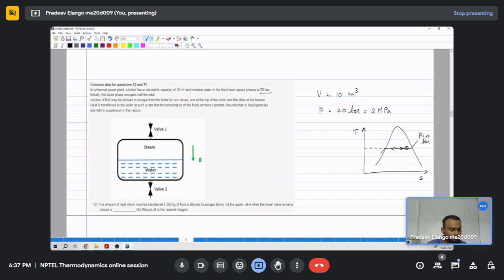In the solution they have given the dryness fraction. So when 300 kg of the steam is taken out and that enthalpy has to be calculated, it should be m into h, and that is hg. This is what you are mentioning, right? 300 into the enthalpy at this state, 20 bar and gas state. No, for enthalpy they have done it right, 300 into hg they have taken, no problem. But while calculating internal energy in the solution, they have calculated the dryness fraction, and it is coming very small, like 0.01. But what I think is that we should also not consider it because of that particular sentence.